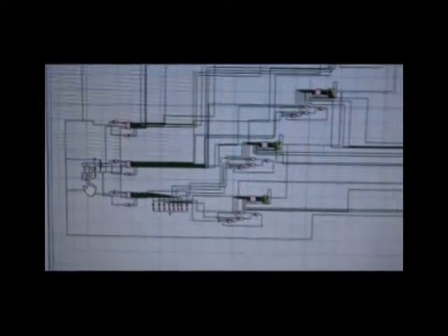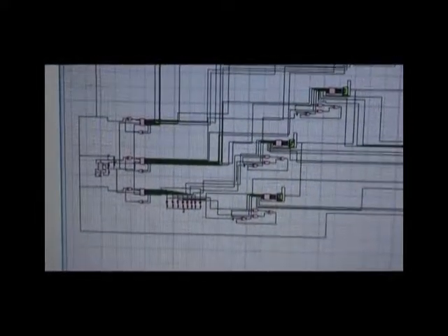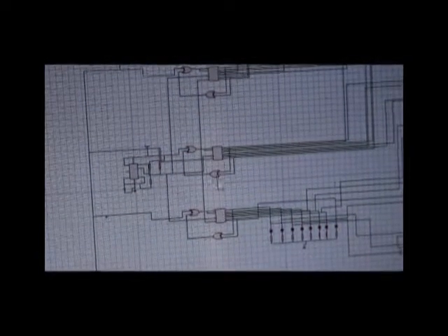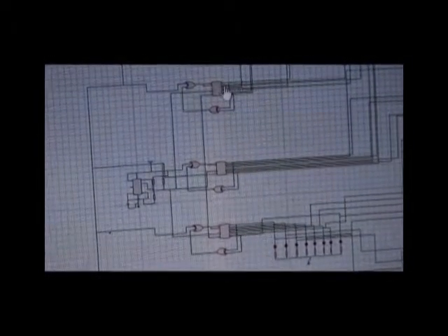Now this Proteus design we implement is on the breadboard, not in the PCB, but seeing this now, we use three 164 ICs. We use 3 164 ICs to generate a 24-bit random signal and send it to the display decoder IC, the 7-segment display decoder 7447, and this is our random number which is generated in this Proteus design,